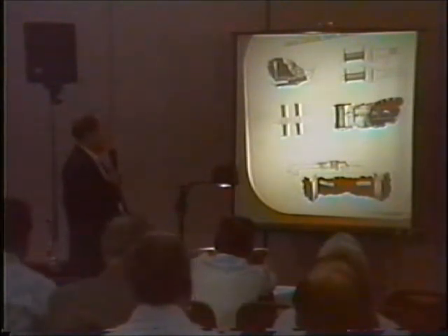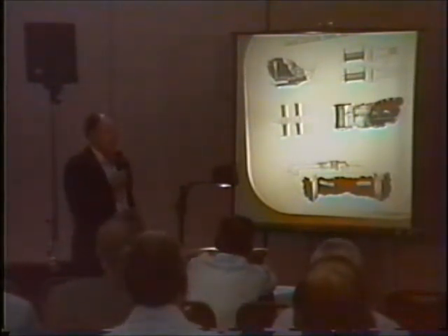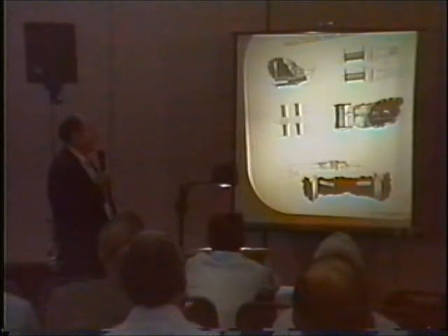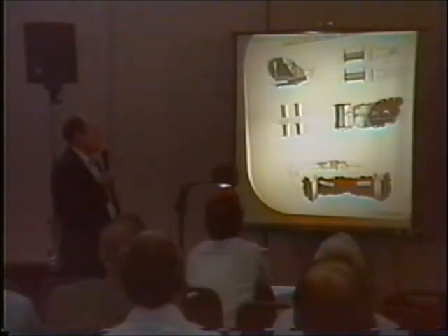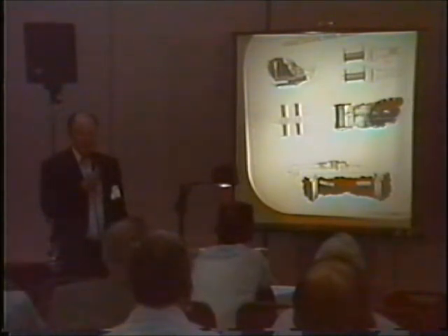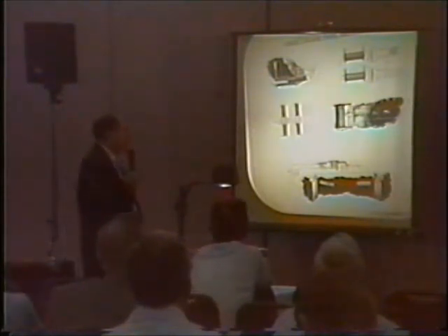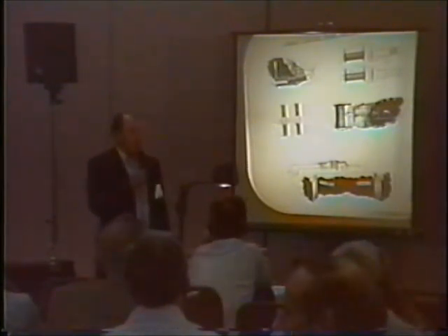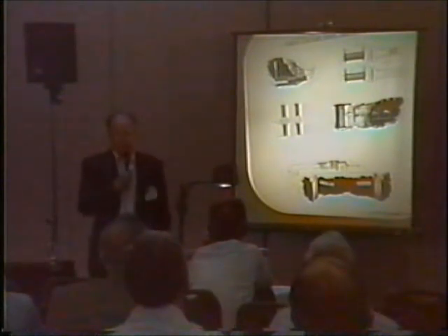Okay, that's your number one drawing. Number two drawing is showing the capacitors combined with the output, and the top one is set up so that you can run a conventional transformer directly. And if the frequency of the coil is something other than what you want, on that number 2, just slightly above where the number 2 is, you can put a resistor or a capacitor in parallel across that particular coil, and you can bring the frequency down to where it will match your transformer.